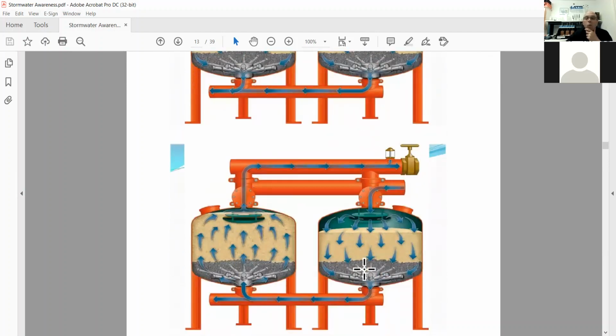Here, we're coming into one filter. We've opened a three-way valve here, so water cannot flow into it. It can only flow out through the backwash. Part of the water will go to discharge, and part will be used to push the backwash flock out.